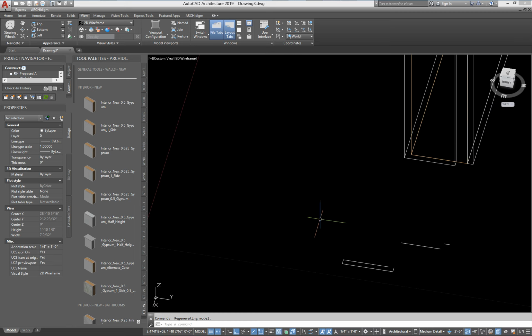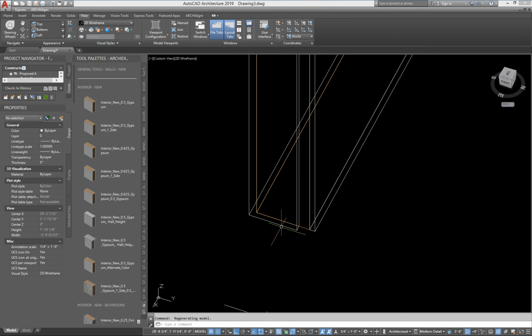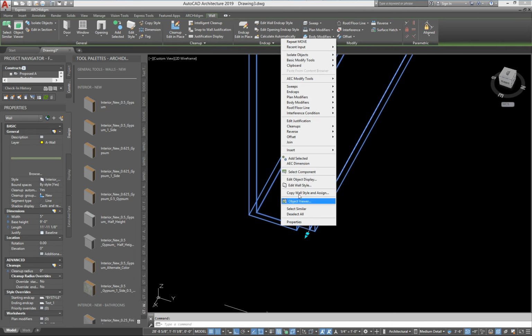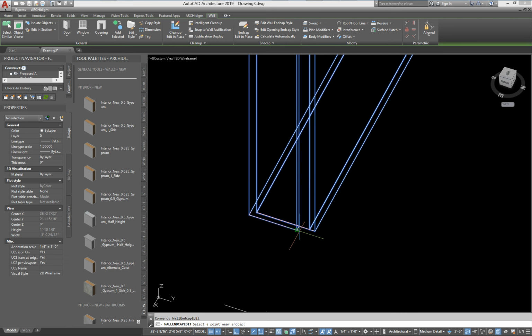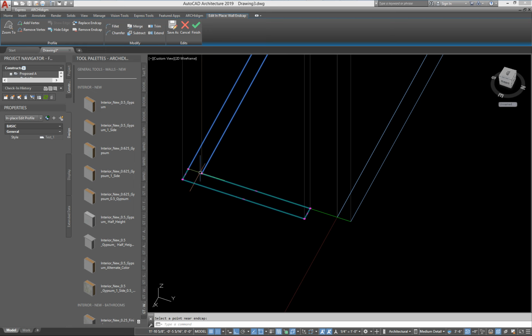What you can do is get yourself into a 3D view, okay, and then you can select the wall. You can go up here to end caps. You can say edit in place and come down and snap to the bottom. So now you can edit that end cap that's problematic. Now, this doesn't always work. There are times I run into problems. It won't let me edit the end cap that I want, or I can't snap it in the right place, or the save as is not functioning right. But on the simpler ones, like this example here, it's pretty easy to do.